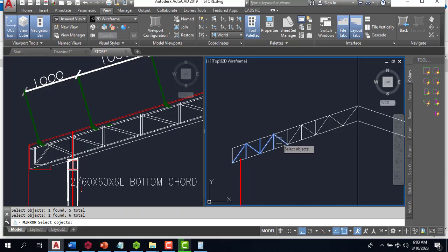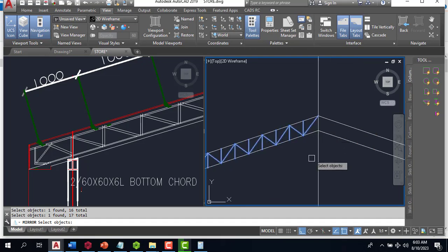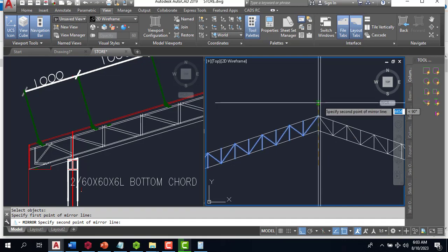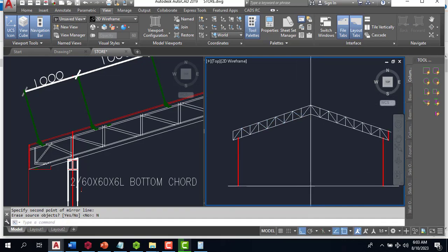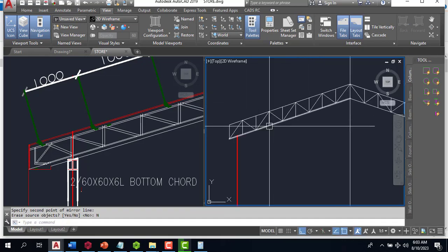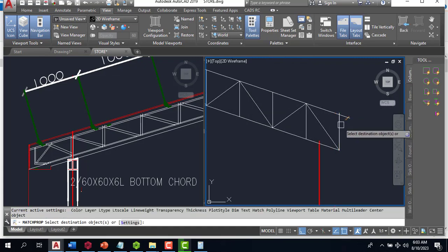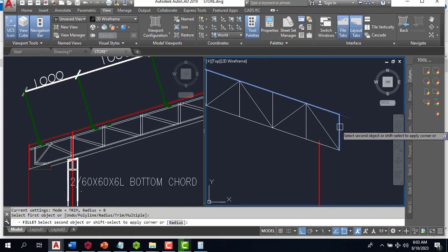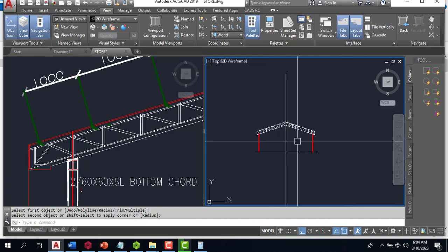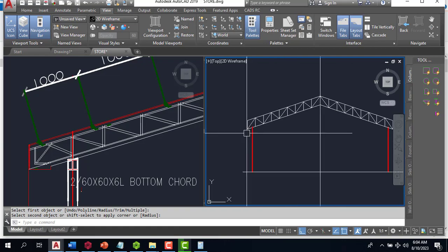But you don't have to do this yourself. The architect is supposed to provide the cross section for you. Once this cross section has been provided for you, all you need to do is just clean it very well and make it in a single line, so that ProtaStructure is able to actually interpret it well.